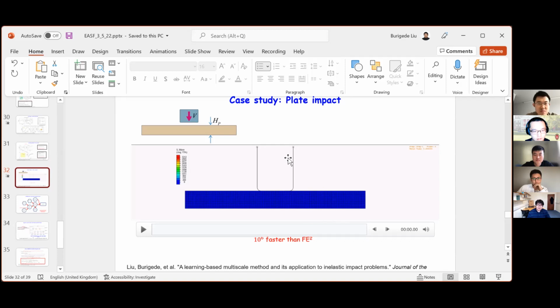Even if you have a round angle, you will still have an asymptotic field, although it's not going to infinity as the elastic solution would be. But again, I want to draw attention that this is not a pure elastic calculation, it's elastic-plastic, with hardening and all that, which complicates things.